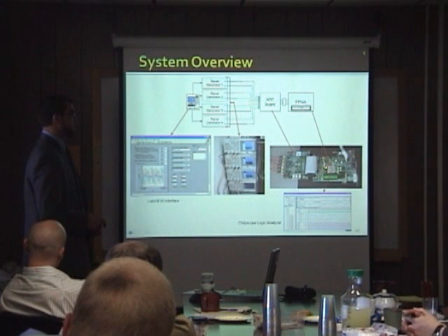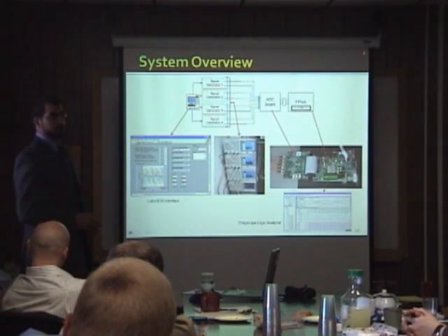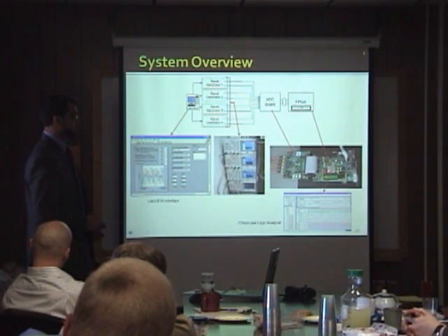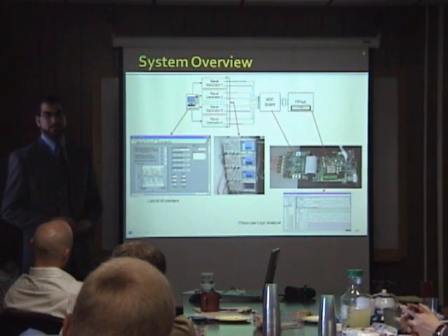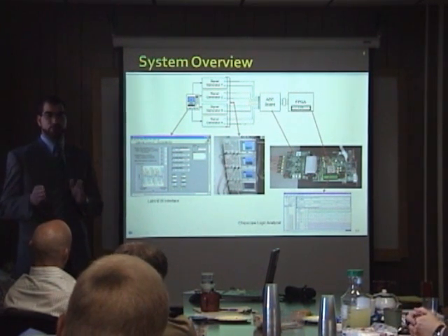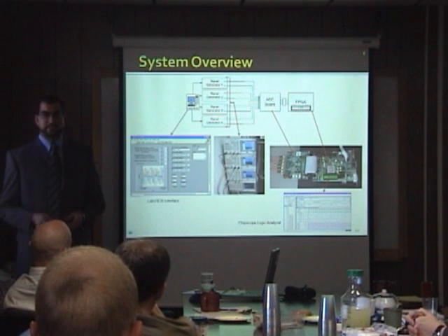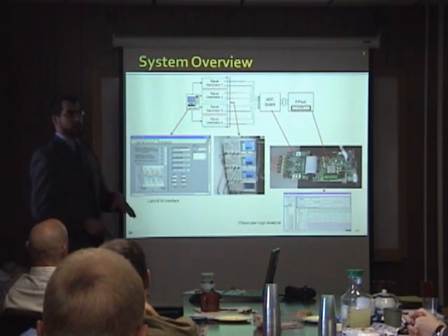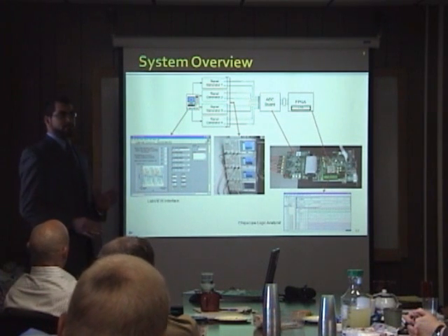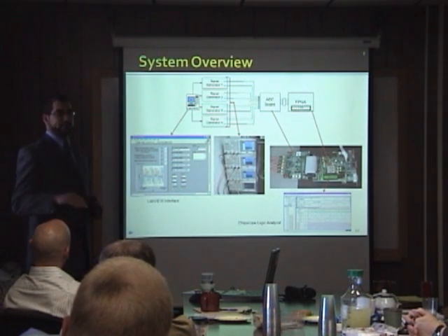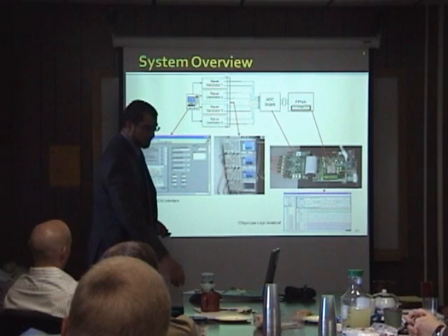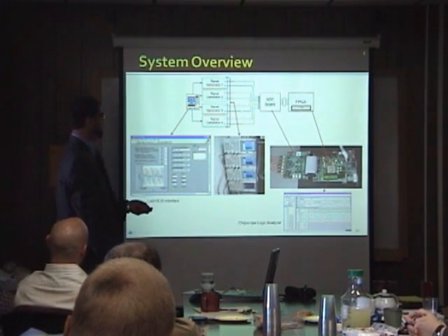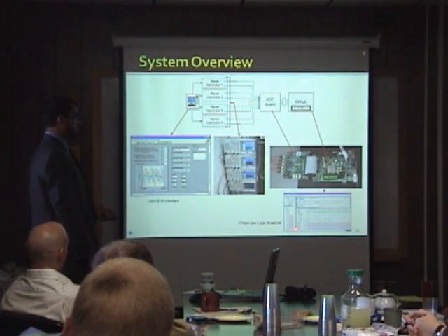So the FPGA would receive, for each channel, a serially sent stream of bits. The FPGA packages those bits into bytes that represent each sample. But all 8 channels are digitized simultaneously. So the serial part is only for streaming the bits.